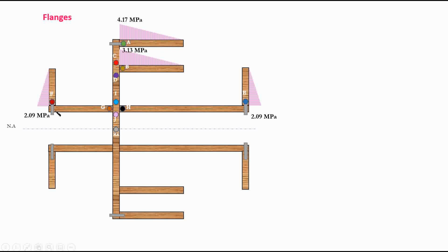You might think that it starts with 0. But the thing is, at this connection, we already had this 2.09, right? So there is a connection. It's not 0, right? Why? Because we already have a shear plane in contact, and the shear stress in this connection was 2.09, as we calculated before, right? At point F, we had 2.09. So we do not start with 0, because we already have a shear stress value. So we say it starts with 2.09 and it goes to 3.13, which was the value we had here, right?